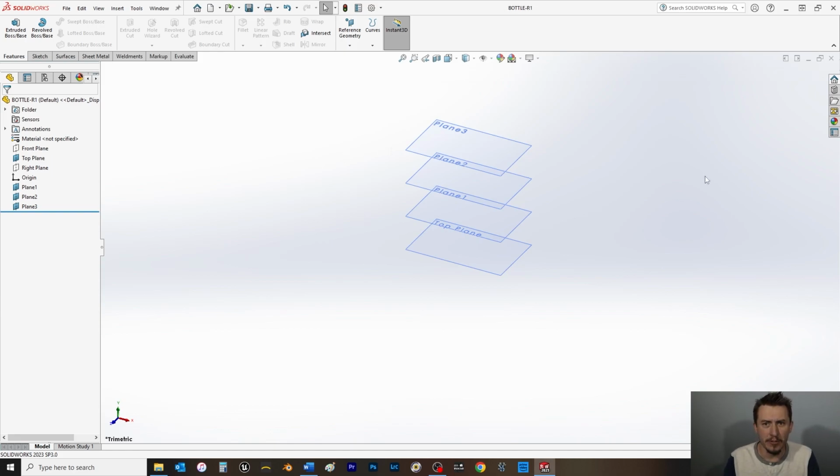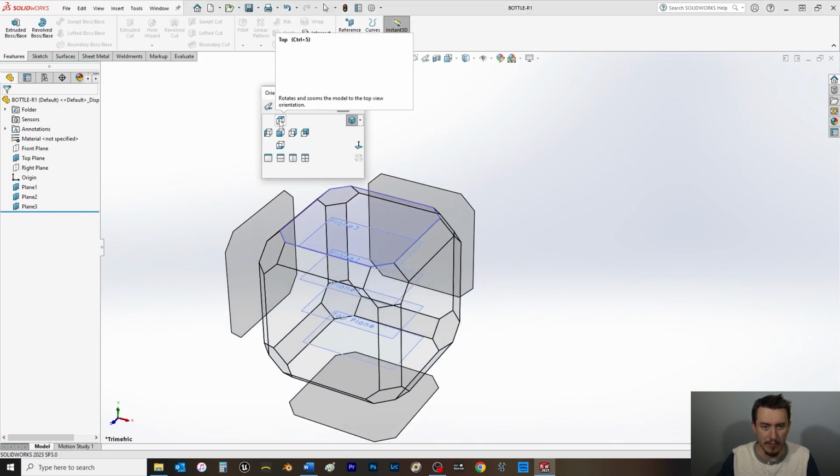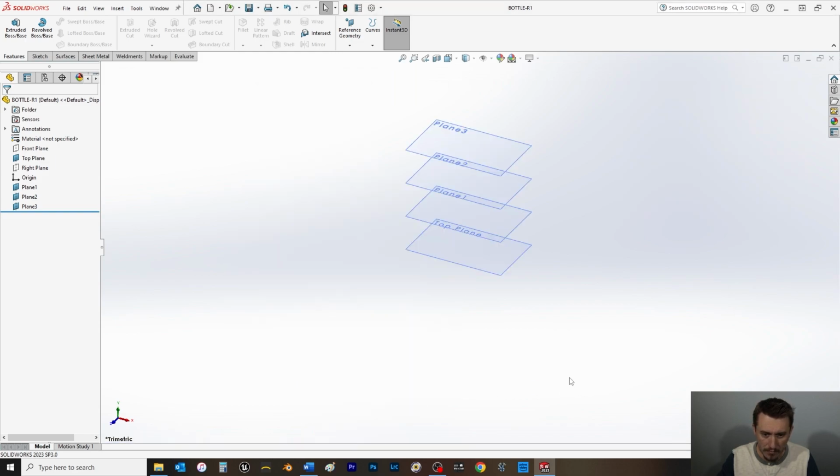Alright, section 13.3 at the top of page 296, we're going to start our first sketch. So, to do this, you can either click on the top plane, or in the graphics view, you can hit the space bar and bring the top view normal to. I personally like selecting the item I want to bring normal to whenever possible. Item being a plane, a sketch, a face, feature, so on and so forth. And the hotkey to bring this normal to, Control A.